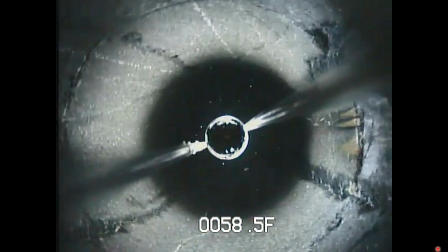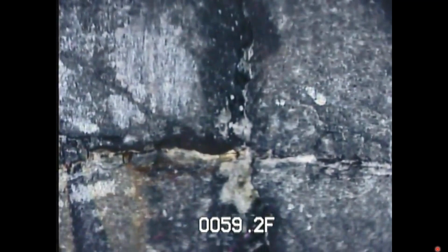So moving into a brief video clip of our downhole camera in action, moving down the borehole, it has the ability to look straight down, but then also turn 90 degrees and rotate, panning from left to right, looking at the full 360-degree view of the borehole. And so taking our core log that we talked about earlier, we can zero in on some of these features.